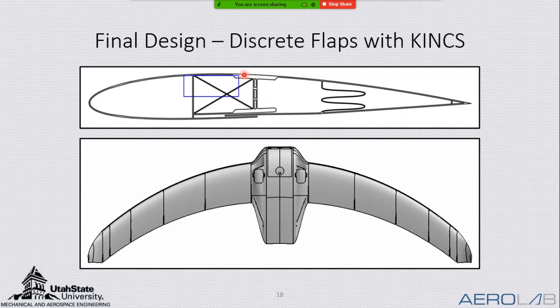Shown here is the I-beam that we developed for the structural support, which we'll get into a little bit later. But you can see this white space that is 100% infill 3D printed with material with these 3 holes in the I-beam. And so on the bottom here is shown the Horizon aircraft, the airframe used to demonstrate yaw control. And this aircraft uses these kinks mechanisms. You can just see the discrete control surfaces, and we'll talk a little bit about these slits that you can see later on. But these discrete control surfaces are cosine clustered.